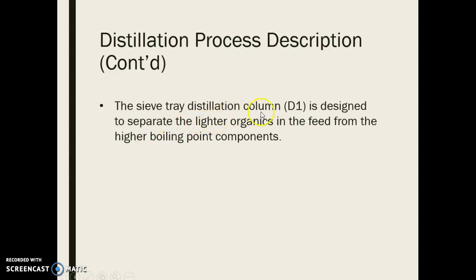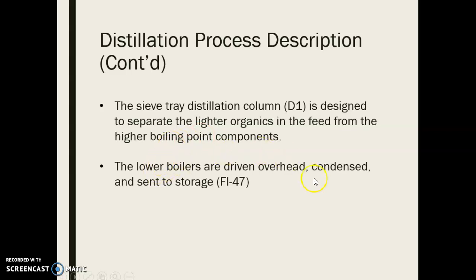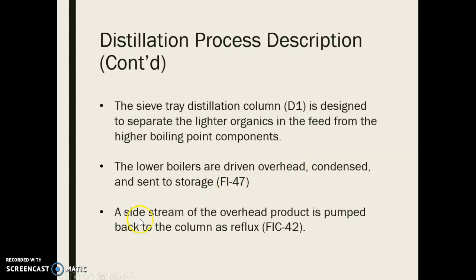Okay, the sieve tray distillation column D1 is designed to separate the lighter organics in the feed from the high boilers. The low boilers are again driven overhead and condensed and sent to the storage. If you look at your paper, FI47 indicates that flow. There's a side stream of the overhead product pumped back to the column as reflux, FIC42. Reflux is really important to running the column and making sure that we get really good separation.